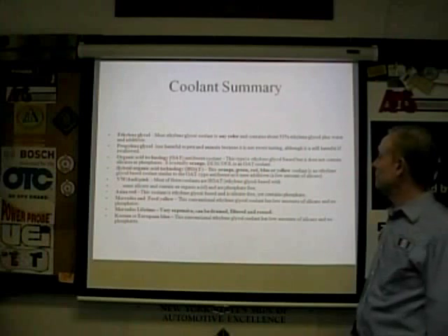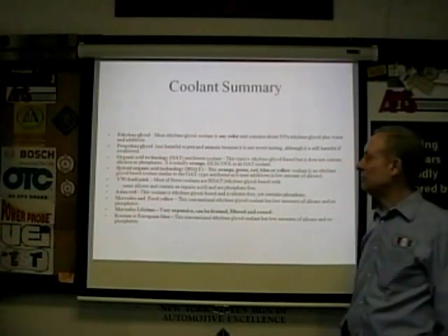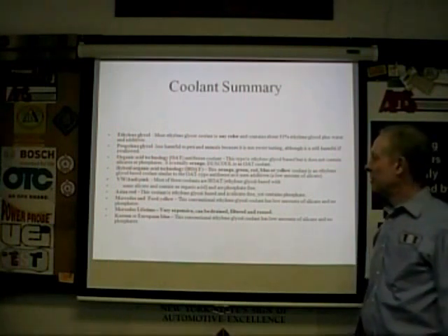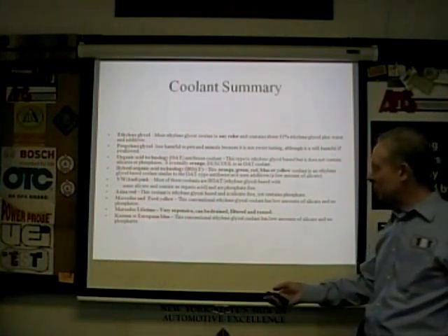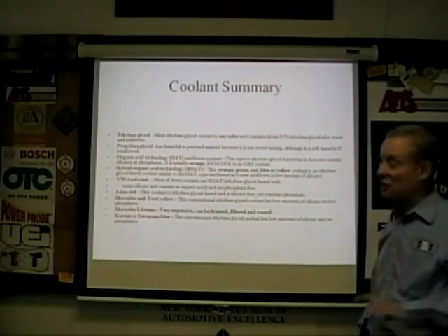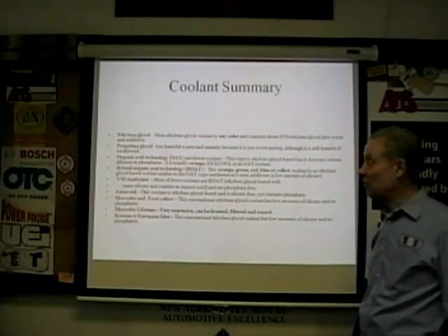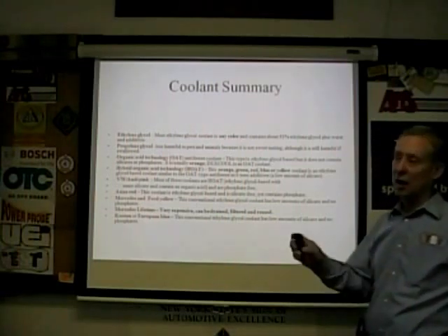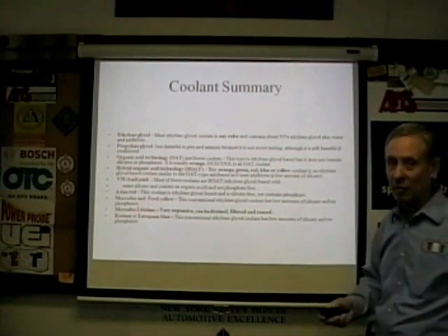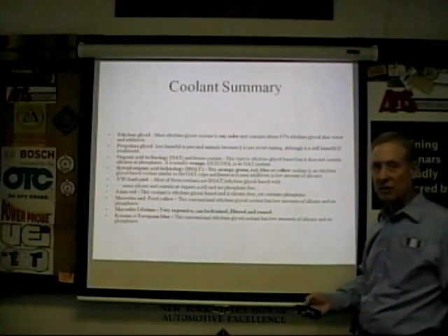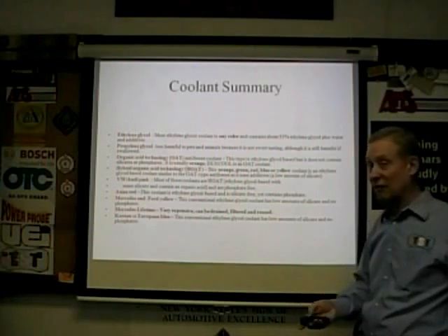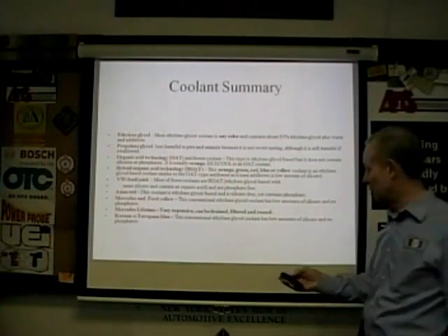Comes in a variety of colors. The color is only a dye. Actual ethylene glycol is clear. It's colorless. You have all these different additive packages for these manufacturers, and they all have their own specs, and the specs have changed over the years. As a rule, I think it's pretty much universal, this rule. Every manufacturer that's come up with a new spec has made sure that it was totally backwards compatible with their old stuff. Unlike oils, where there might be a little difference, with the coolants, I'm sure that's actually true. They meet all the old specs.